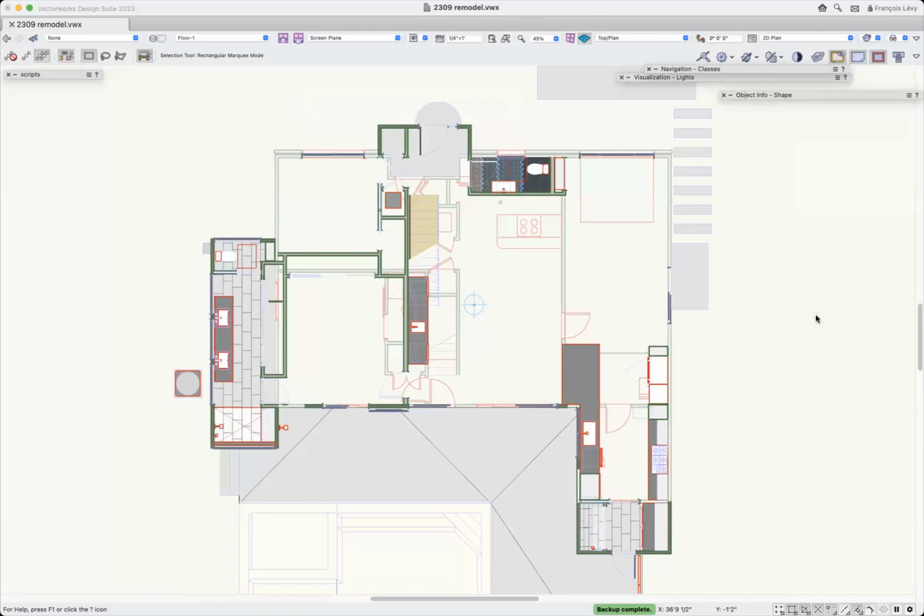the way that I would approach your conundrum is, the first thing that we do on a project like this, of course, is we generate an as-built file. And that's obviously the basis for our design work. And so if you needed to show the existing conditions, what I would recommend is that you create an as-built layer in your file that is not part of your story schema. It's sort of off on its own. Okay. And that you go ahead and viewport in your as-built file.